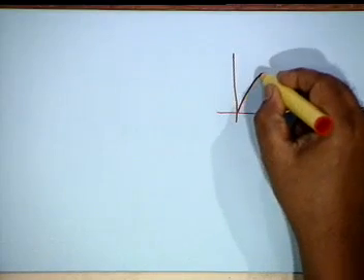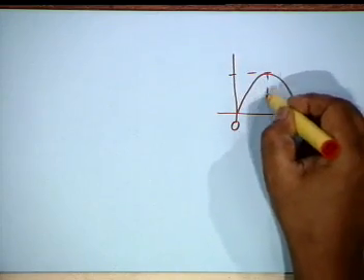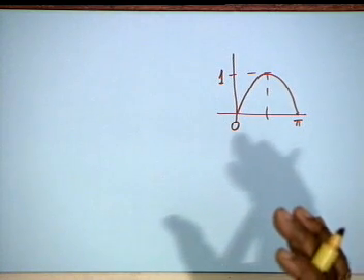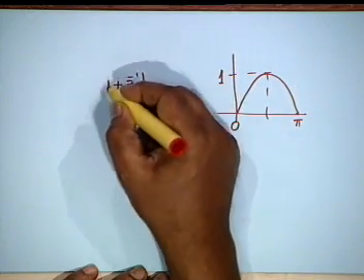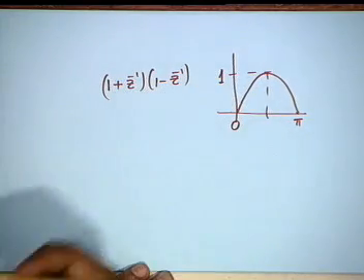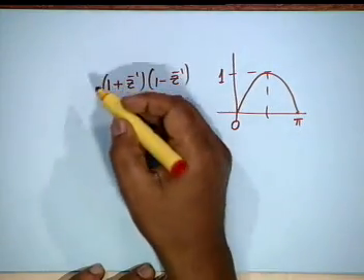Now, the next thing I am asking for is a bandpass filter. What I want is a characteristic like this. At pi it should be 0, at 0 it should be 0, and somewhere in between it should be 1. Obviously, one of the very simple things that I can do is to cascade a low pass with a high pass. That is, if I have 1 plus z inverse and 1 minus z inverse, shall I multiply by 1/4 or half? We will see what the multiplication is.